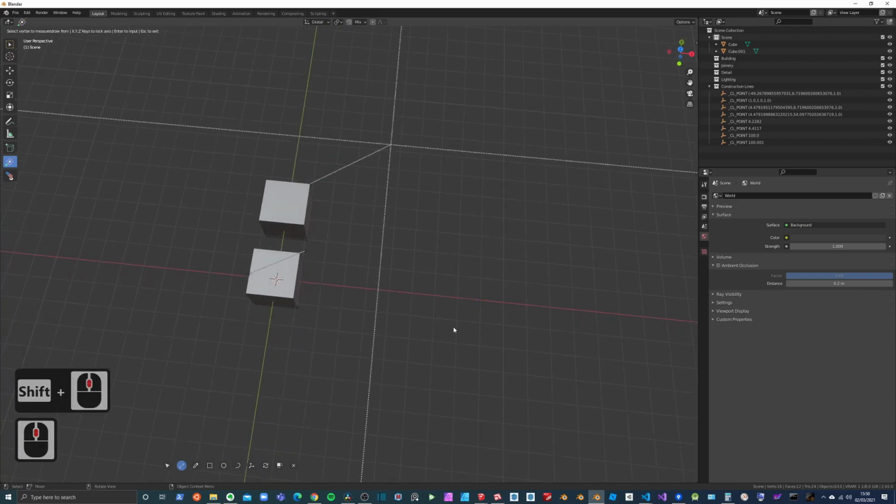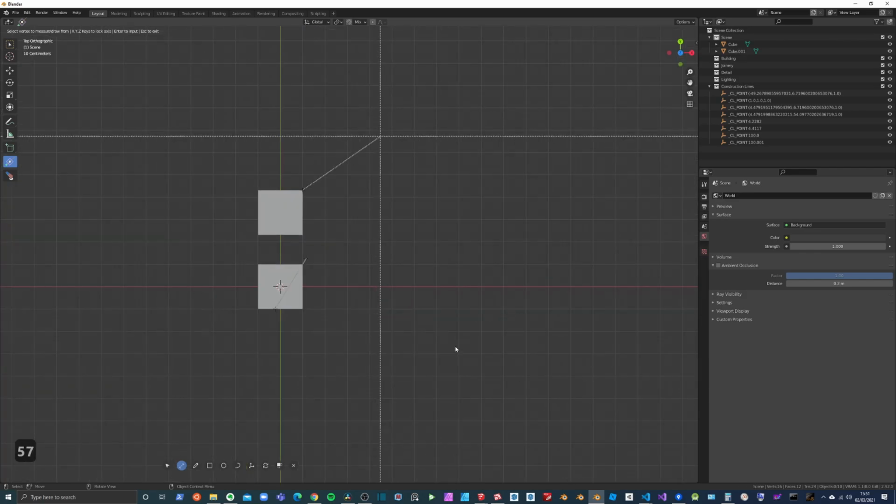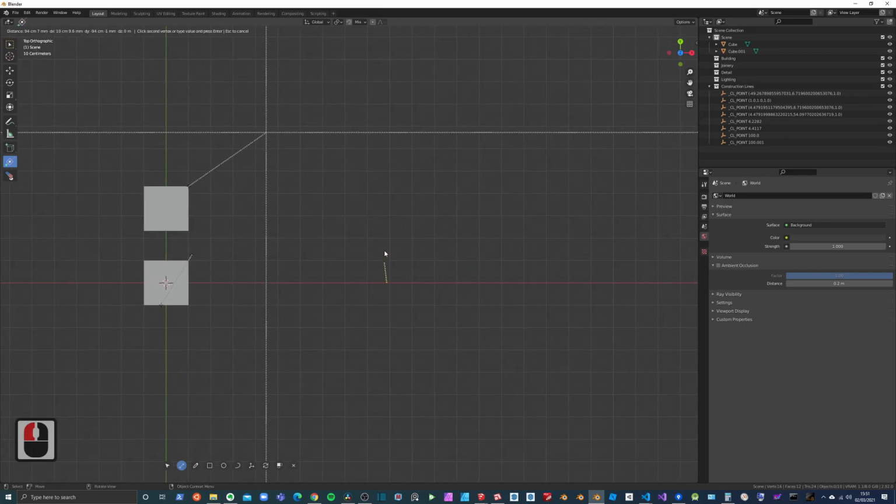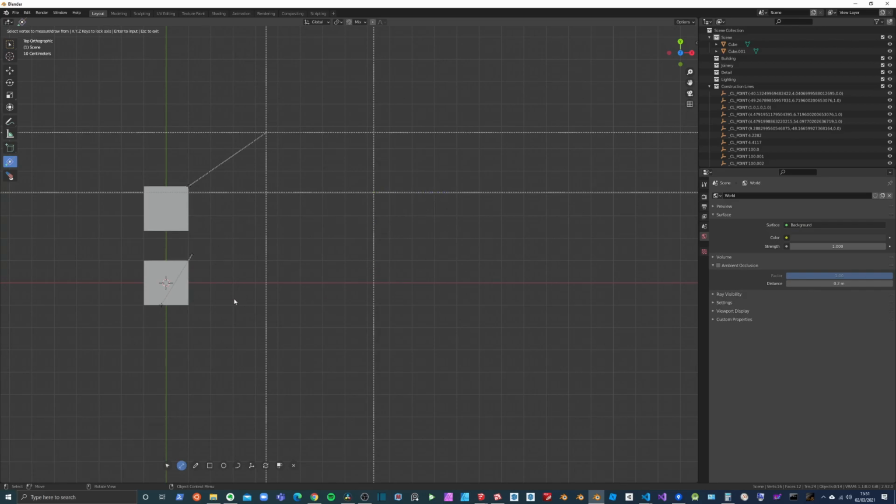Another new feature that I've included, which you might have seen whilst I've been moving around, is that you can now snap to the global axes. They're treated like edges now. And again, if I go into top view, I can now start building guides, maybe horizontal guides, straight off of these axes. And this is really handy, especially when you're starting out a scene and you've not modelled anything yet, and you want to set your space out and your dimensions. Instead of just working from the 3D cursor as we did before, you can now work off of these axes.